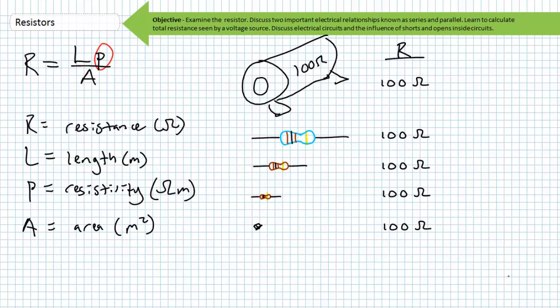I'm not going to use a surface mount resistor to carry a lot of current. I'm going to use a big old wire wound resistor with a ceramic tube to dissipate heat. In short, physical size of a resistor has nothing to do with resistance and everything to do with power handling capability. Physically larger resistors have higher power ratings.